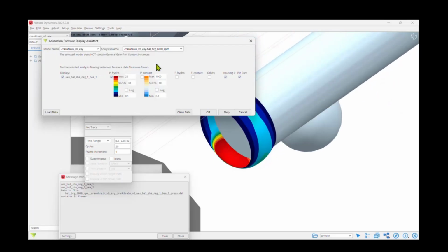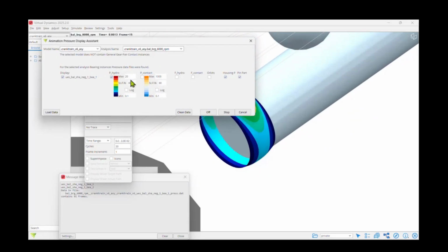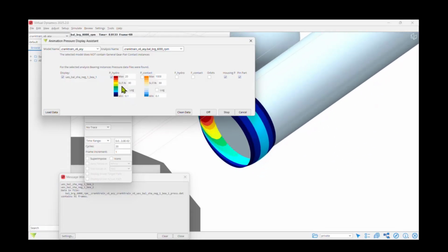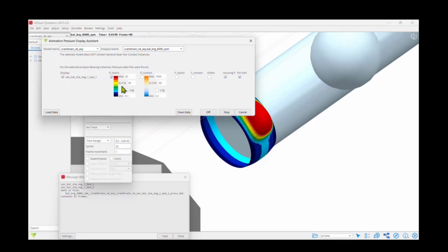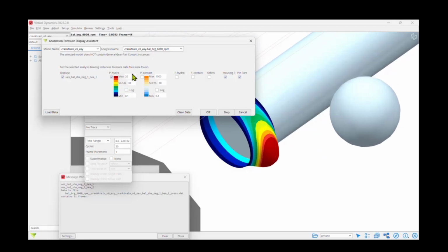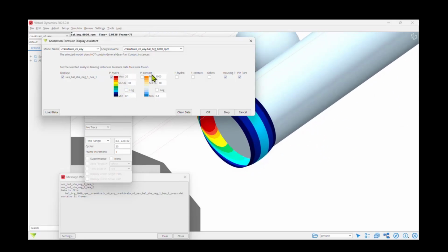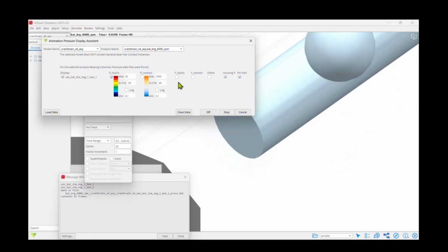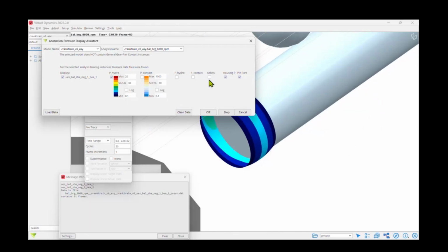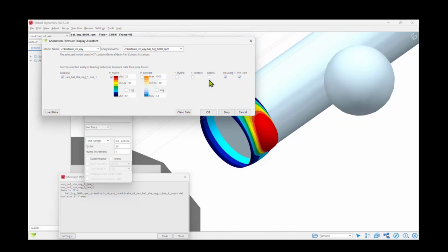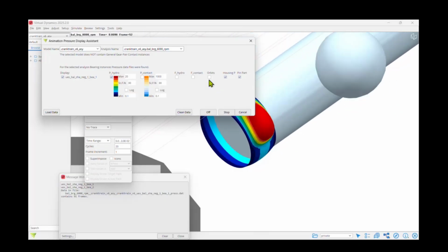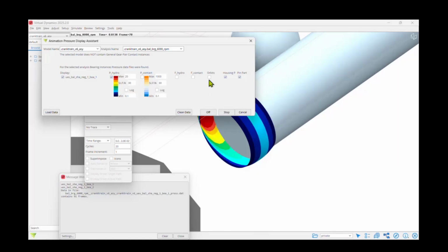In the dialog box, you can adjust the max value and min value to display, and also you can use a scaling factor to improve visibility. Separate maps can be plotted for the hydrodynamic and contact pressures. Additional overlays such as the hydrodynamic force and contact orbits are also available. This is usually the moment users realize that static plots miss part of the story.